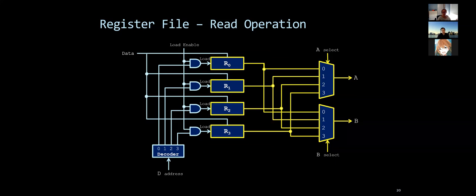So essentially, there's a signal that tells us read or write. The decoder can be implemented differently, not necessarily a demux. It can be more complicated than that, but in the simplest version it is. Okay, this is a register file. I hope you already get a feeling why, even using the same technology, I cannot easily make it super large. It's not a trivial task. So essentially if you make it large, the latency will go up, right? And that kills the whole purpose.